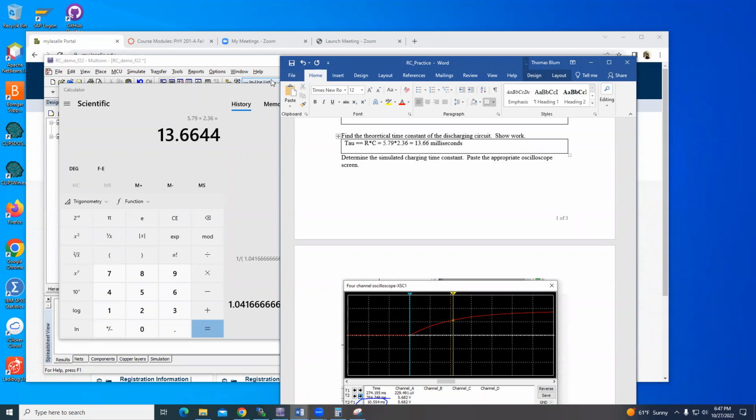And there is the problem that the resistors in the charging and the discharging circuit are different, that's one thing. And the other thing is that resistors and capacitors combine mathematically in the opposite ways. So resistors in series add, but capacitors in parallel add. Okay. And the simulation part is maybe a little bit more difficult because you have to know what to do with the oscilloscope.